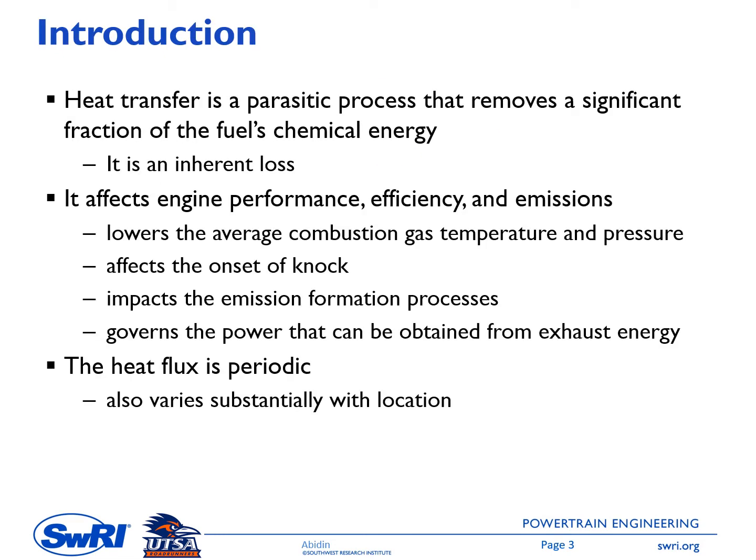Heat transfer is a parasitic process that removes a significant fraction of the fuel chemical energy. It is an inherent loss in an internal combustion engine, so we cannot remove this heat transfer completely. We can reduce it by a certain device or by a new design of the engine. This heat transfer affects the engine performance, efficiency, and emissions.